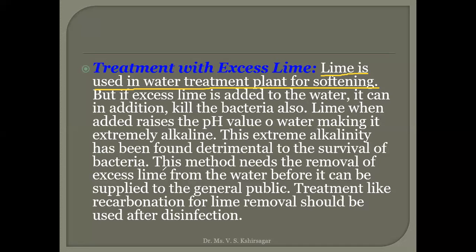Also, because of the addition of lime, an excess amount of carbon is generated in the water. For that purpose, you need to go for recarbonation for the removal of the lime which is used for the disinfection purpose. These are the multiple drawbacks with respect to lime, and that's why we don't prefer lime addition for the disinfection purpose. Understood? So the first method, boiling.